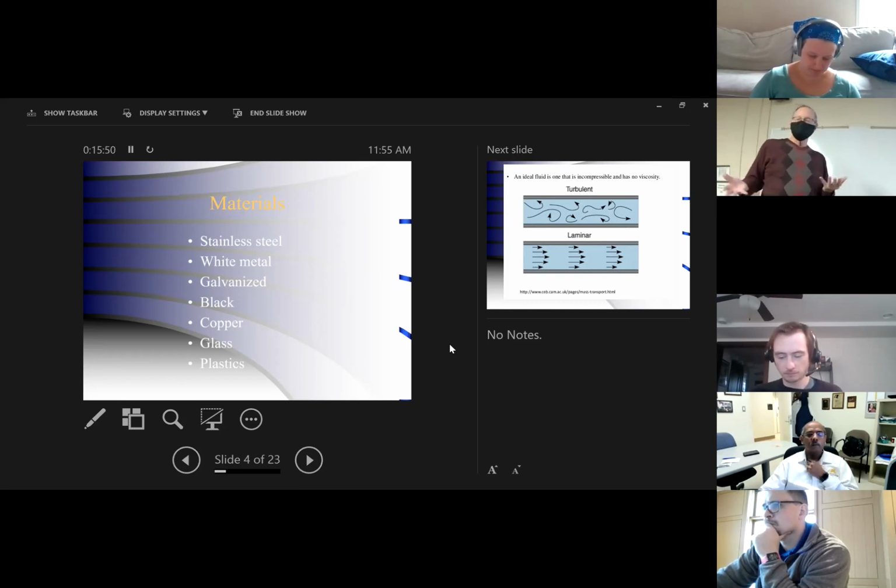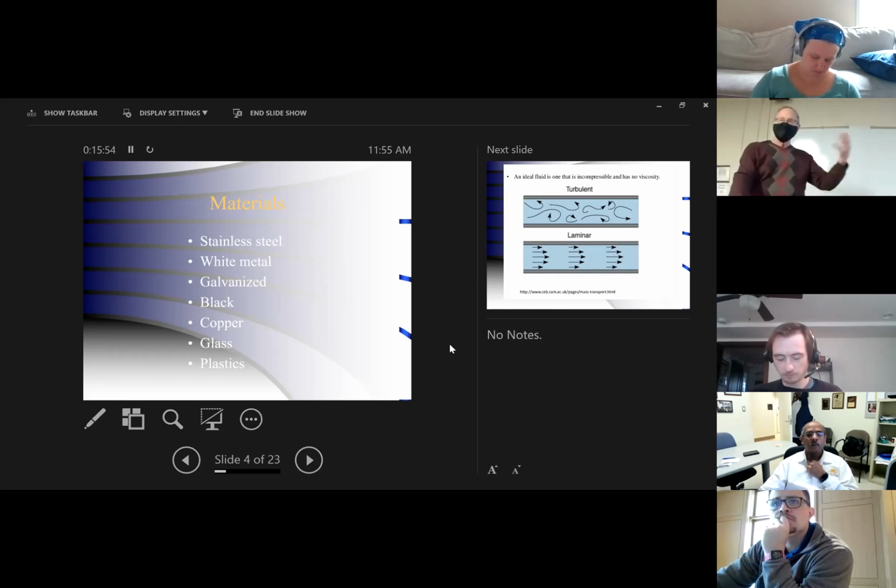By and large, people would probably use 303 with a number 4 finish. You don't gain a huge amount with a 5 to a 7. Besides, after you clean it a few times and other things, you start to lose a little of that shine anyway. And so, while it might look prettier to begin with, probably not worth a lot as far as sticking all that extra money into it.